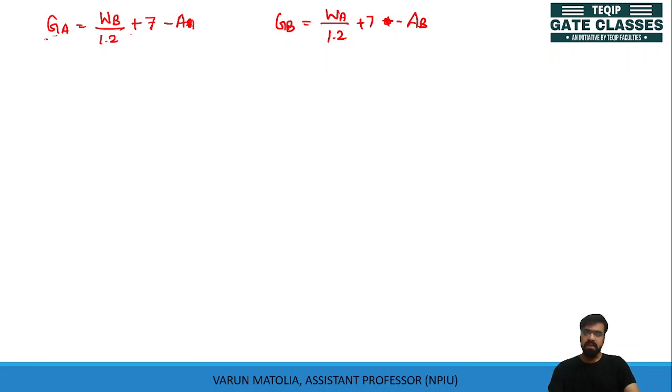You have green times for your sections, but is this time enough to allow the traffic volume which is there on the road? To check this, let us take the ratio GA by GB calculated here and equate it with the traffic flow in A direction by traffic flow in B direction.